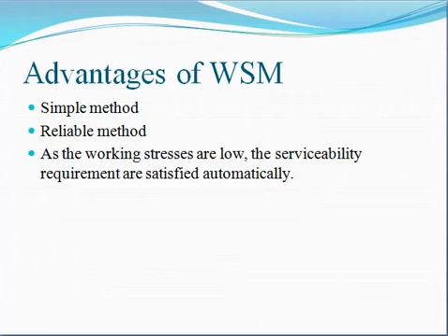And the third one is, as the working stresses are low, the serviceability requirements are satisfied automatically. What is the meaning of it? In case of the working stress method, the stresses are very low, so the design is serviceable. Means there is no need to do another design step or provide additional steel to account for serviceability. No need to go for that. These are the advantages of the working stress method. Now we will see the limitations.